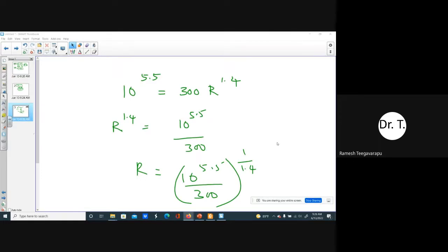Of course, this is given in the form of intensities. So if you were to multiply by 6 minutes or 7 minutes, depending upon how much time the radar will take to complete one rotation before the reflectivity value changes, you can actually calculate the amount of rainfall that is available.